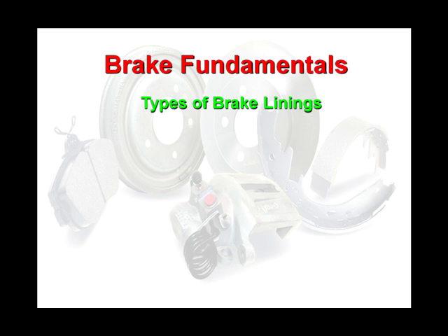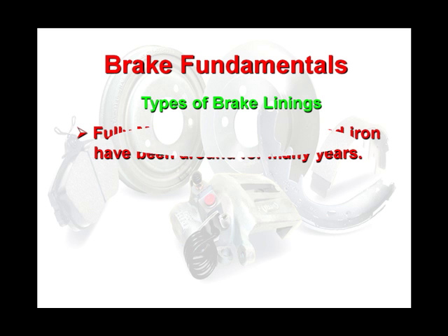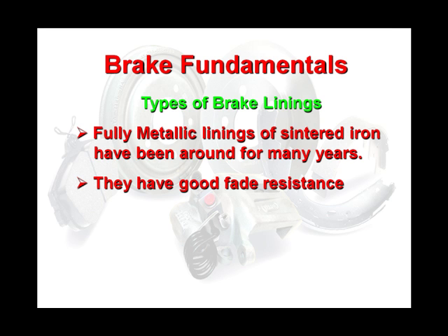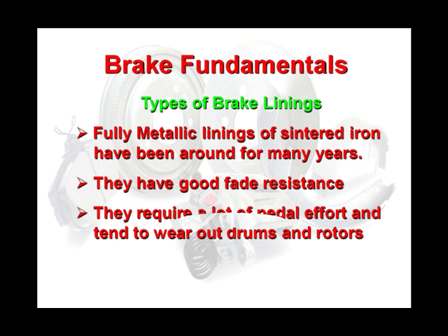Types of brake lining. Fully metallic linings of sintered iron have been around for many years in heavy-duty and racing applications. That's because they have great fade resistance. However, they require a lot of pedal effort and tend to quickly wear out the drums and rotors.